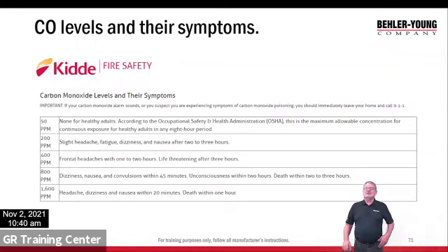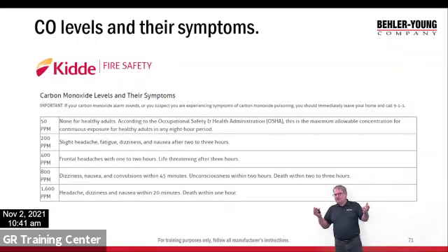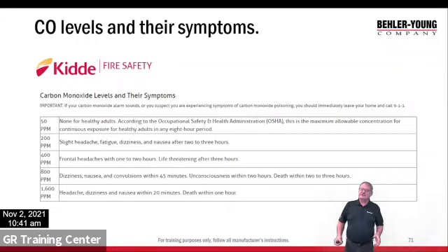Okay, so again, we don't want to be afraid of this. Education is everything. We need to understand this. Okay, we can prevent this. This is simple to prevent. All right, that perfect combustion we talked about, we need to understand that. We need to address that. We take care of this. All right, it's pretty much that simple. Do I have enough combustion air? Do I have the right amount of fuel mixture? Perfect. Are we venting properly?